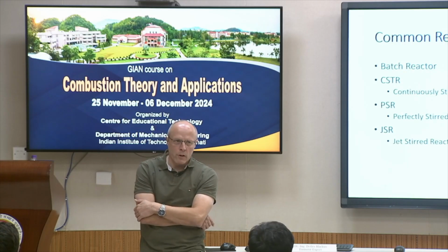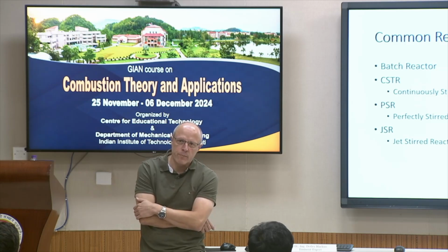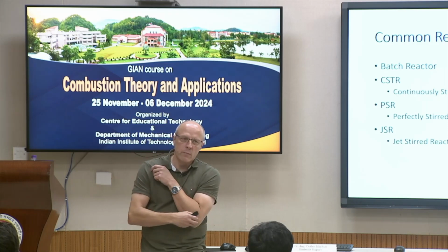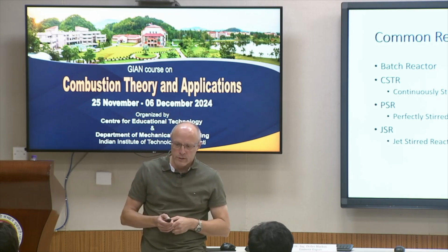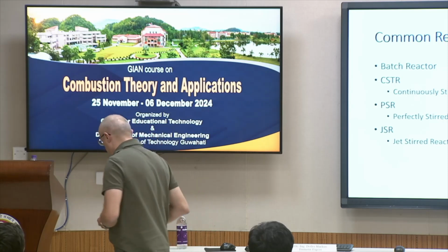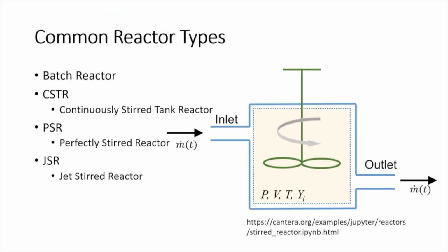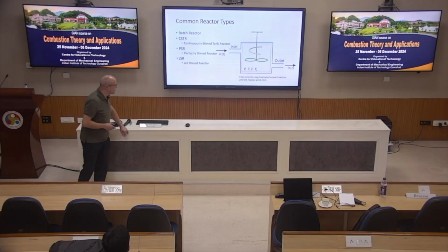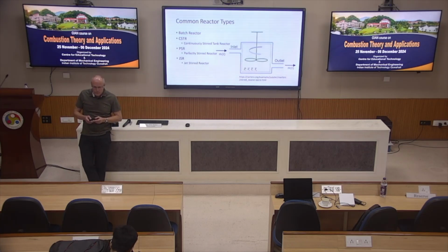So we are talking about 0D simulations here. You solve your equations as a function of time, but there are no spatial dependencies. So the assumption here is that inside this reactor, everything is homogeneous. There are no derivatives in any of the coordinates. You just have to describe your equation system as a function of time.